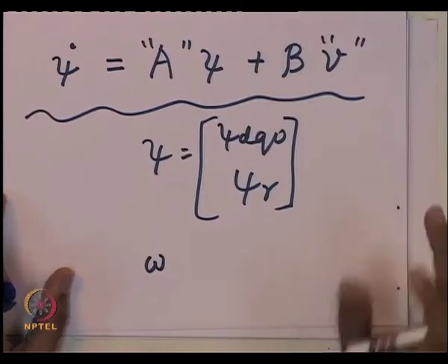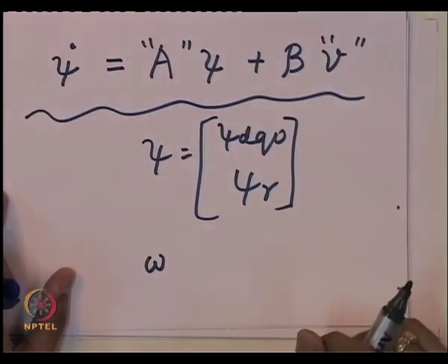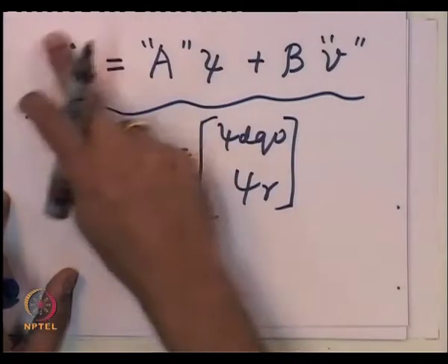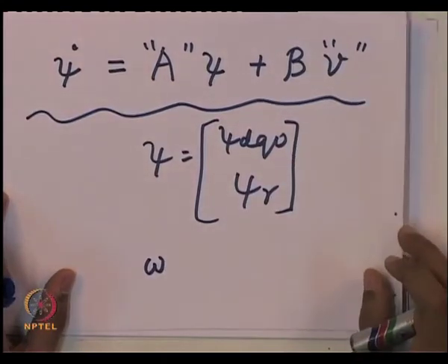Okay. So, that is the beauty of applying the dq0 transformation. If you have constant speed, this becomes a linear time invariant equation. There is no explicit dependence on theta, which itself changes with time. Okay. So, this is one of the main important things which really comes out of applying the dq transformation.